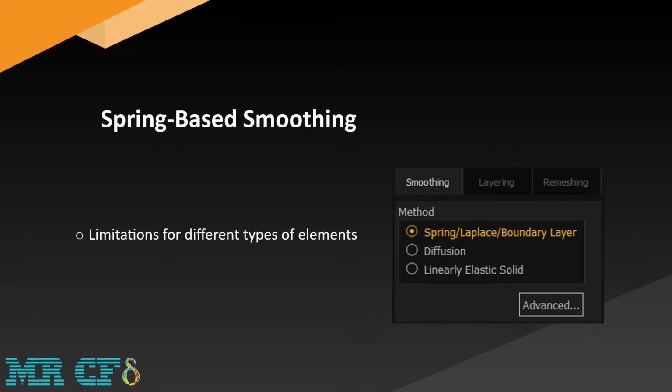However, the spring-based method for polyhedral meshes causes high skewness under any condition, with or without these two conditions. Also, for hexahedral meshes, the diffusion-based method is generally recommended.